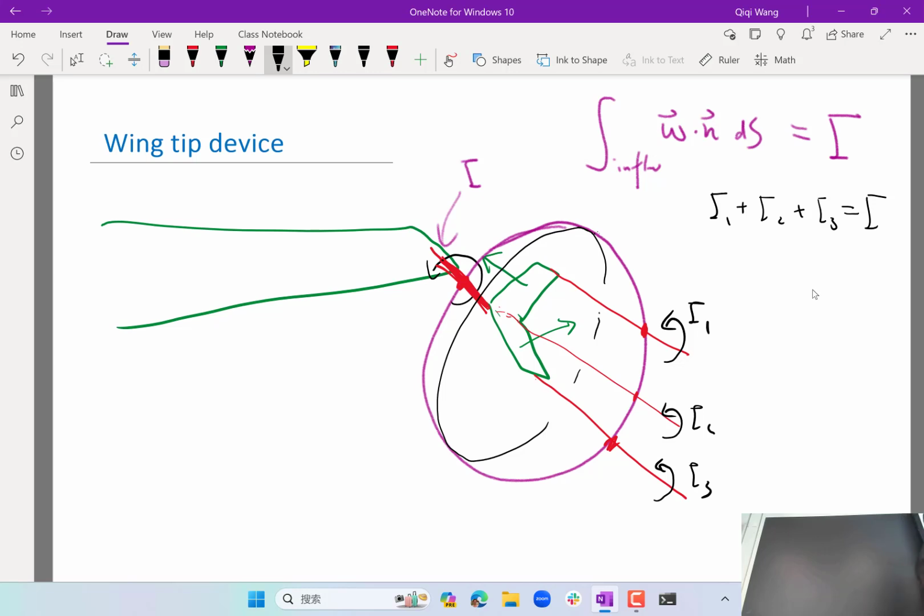Good question. Is there any benefit of spreading out the vortices? In this case, yes. If you remember, the flow around these concentrated vortices has high velocity, right? And by Bernoulli's, high velocity regions have low pressure, right? So that's low pressure. High velocity means wasted kinetic energy. Low pressure means if you do a control volume analysis of the momentum, it creates drag, right?